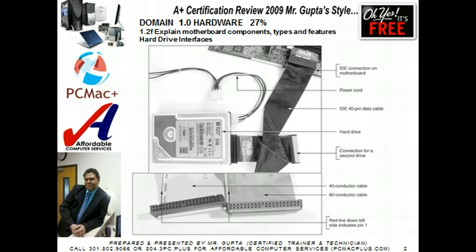Parallel ATA or EIDE drive standards. Parallel ATA, also called the EIDE, Enhanced IDE standard, or more closely the IDE, Integrated Drive Electronics standard, allows for 1 or 2 IDE connectors on a motherboard, each using a 40-pin data cable.